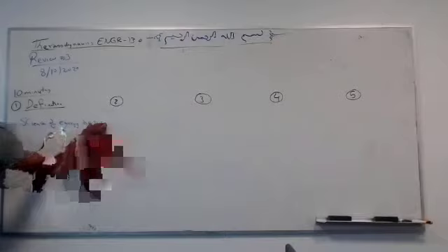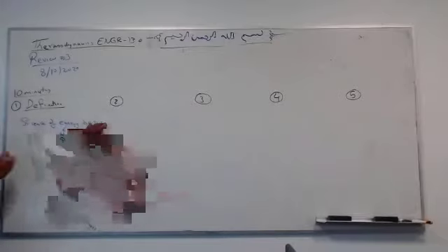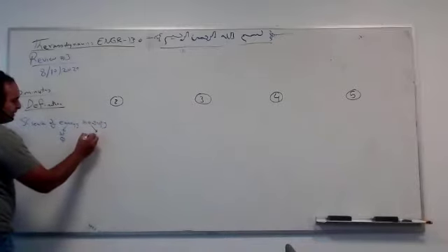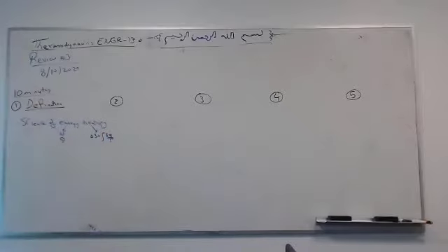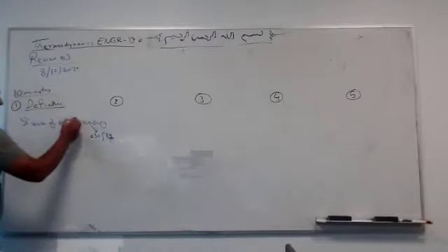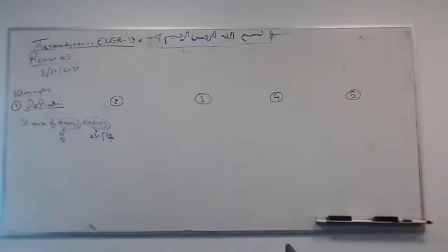Energy can be heat, can be work, can be even mass flow rate with energy added to the system. Entropy, S. For example, delta S is dq over T, which is a property of a system. We talk about this a lot, about the work, about Q, but remember, it's a science of energy and entropy. Something conservative, something not conservative. Something cannot be either created or destroyed, something always increases. This is the definition of thermodynamics, the main definition.